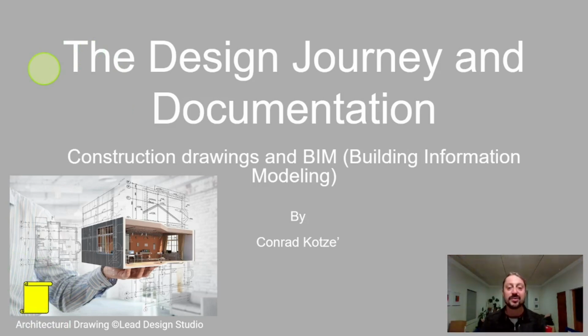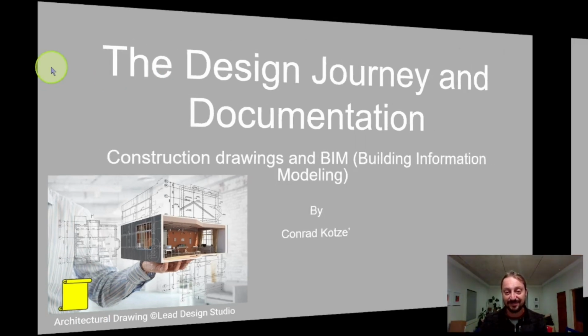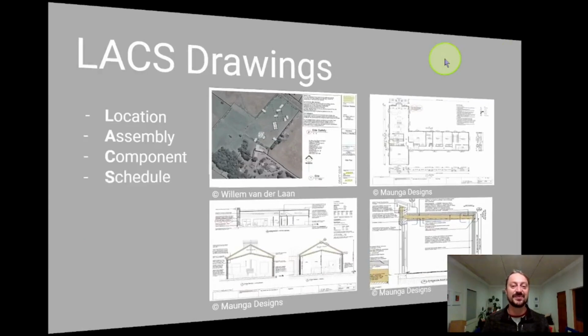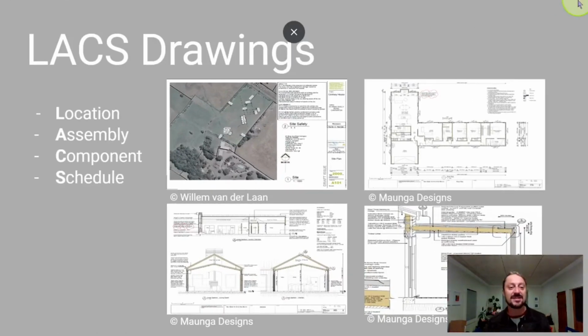Welcome, I'm Conrad Kotze, qualified builder and currently studying architectural technology. There's a variety of drawings found within the construction drawings. We're going to look at each one individually and just touch on them briefly to know what it's all about. We're also going to look at the LAY system, which is a grouping system to group relevant drawings underneath each one, according to location, assembly, components, and schedule.